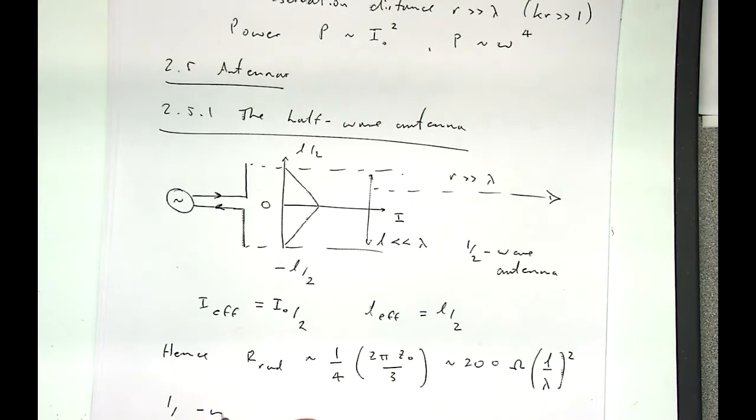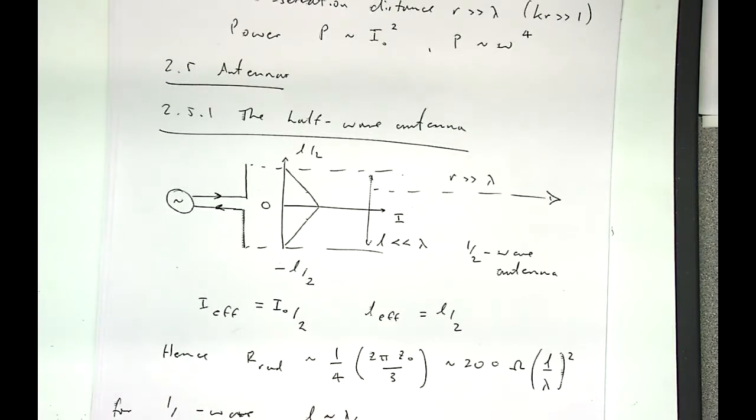That's the example we had before, right? So that's separate from here. This is the half wave. For our previous quarter wave case, where the length of the antenna was about lambda by 4, we have a new radiation resistance, which is of the order of 12.5 ohms. It's lower by a factor of 4 compared to the 50 ohms we had before.